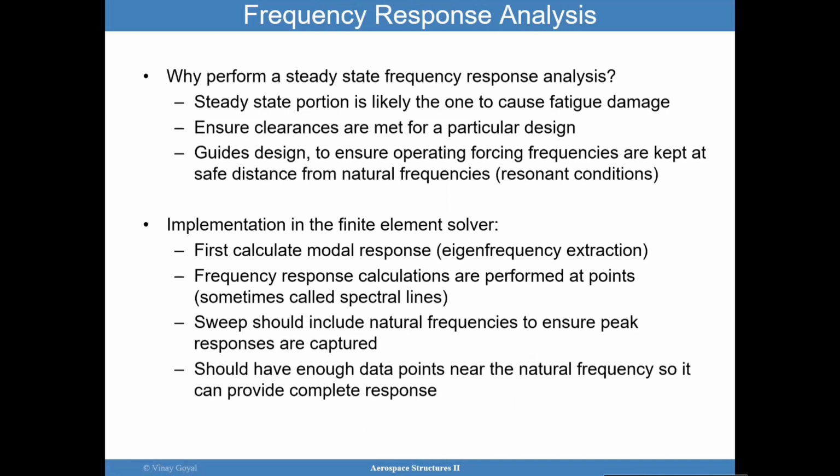You have a partial differential equation, where the variables, deflections, are a function of space, and they're also a function of time, the time domain. And we discussed how that's so hard to solve. So we have to use finite element models because they discretize these partial differential equations and put them in a manner that can apply the numerical ideas that we discussed earlier.